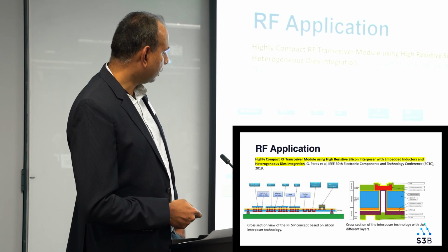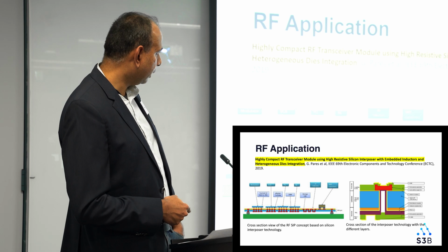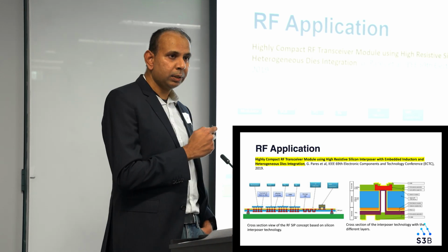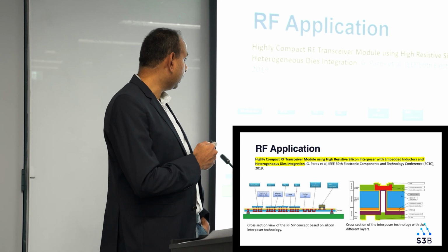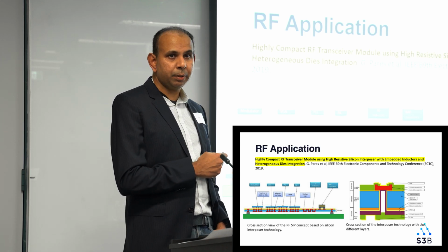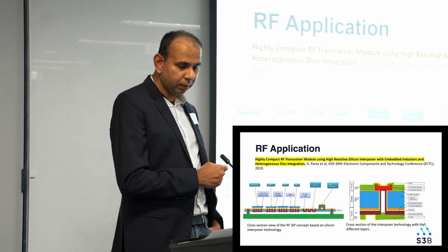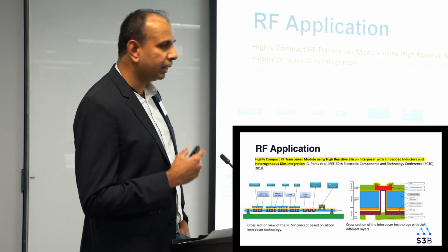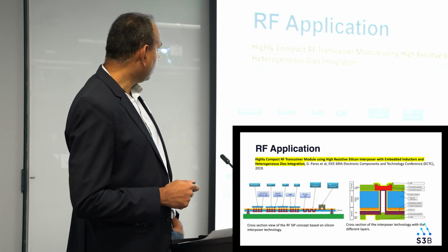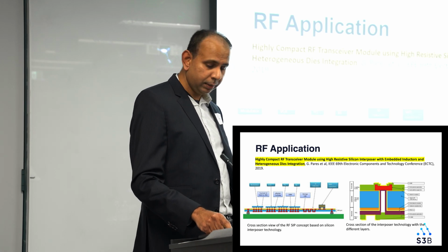Here you could see the cross sections of such an interposer along with your RDL layers and the under bump metal process. One of the key outcomes from this research paper is that they were able to shrink the footprint of the device by 60% going via this heterogeneous integration technology. So this gives an overview of what sort of advantages you can achieve by using advanced chip packaging.